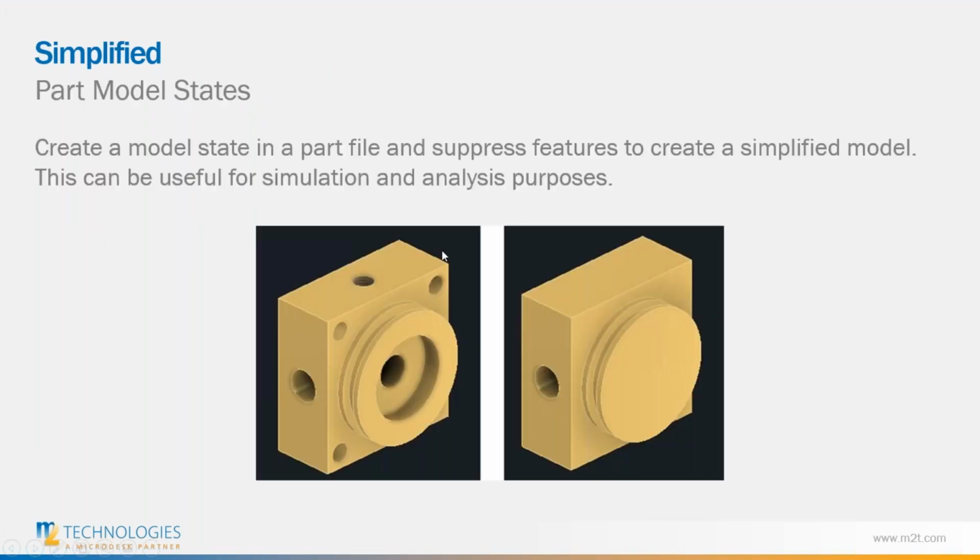And the next thing that we're going to cover is the simplification. Okay, so again, simplification, really important thing for Inventor, especially if you want to reduce the file size, increase performance, or maybe you want to send these components out to a vendor or something like that, and you don't want to give away all your IP data with that data that you're sending out to the customers.